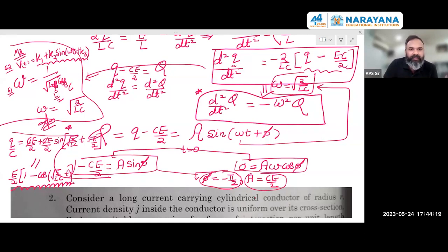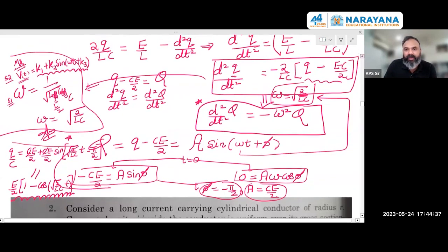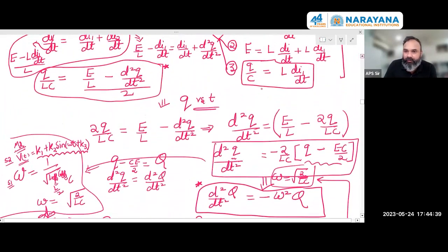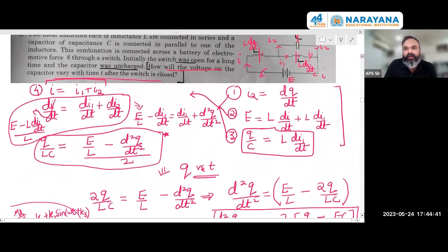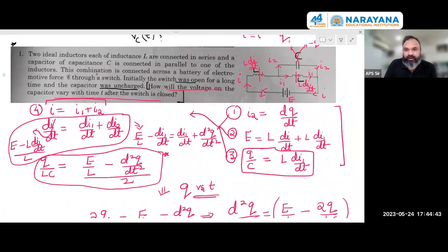Now there are 3 variables, K1, K2 and K3. So basically I will keep on satisfying the initial conditions. That is the initial charge term I'm going to satisfy, right? I am going to satisfy the current term. So I will eliminate 2 terms from there and 1 through any of the equation. I mean, instead of writing all 4 of them, I'll write 1 through any one of them, right? Because I know the voltage.